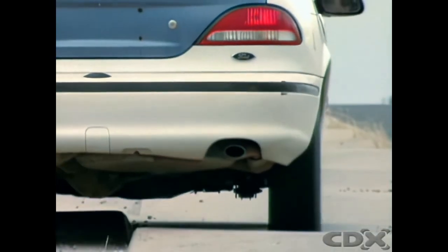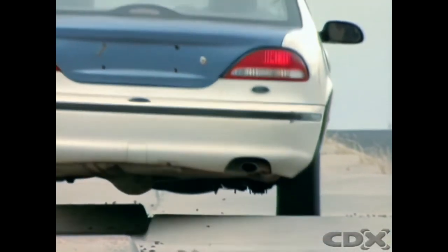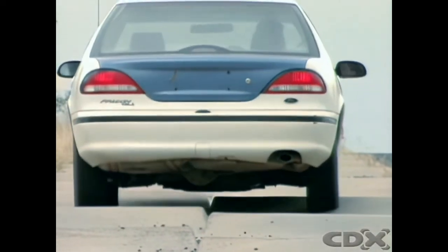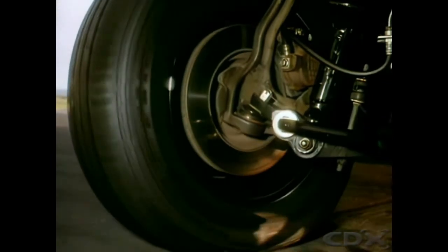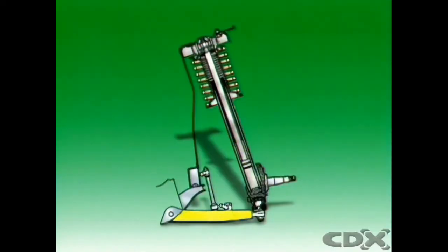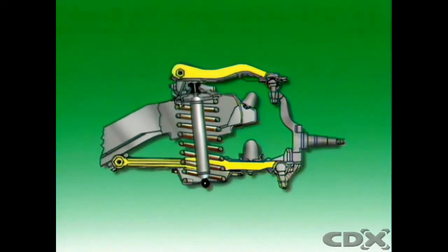The major components of the suspension system must be firmly located to withstand the forces that occur in normal operation. Control arms fasten a component like a rear axle assembly to the vehicle body, while allowing it to move as it needs to. Similarly with a steering knuckle. The arms must be strong enough to withstand the forces due to normal operation, but light enough to minimize the vehicle's unsprung mass. The front suspension can have one or two control arms.